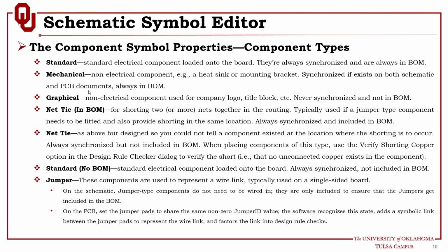It can be only a schematic symbol, it doesn't have to be synchronized, but if you create a heat sink, you need a symbol for a heat sink. It's just a small block, and this heat sink has to have a physical representation on the layout as well, where you need to place the heat sink.